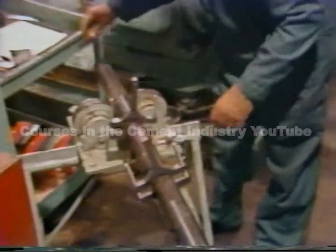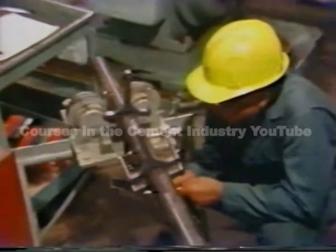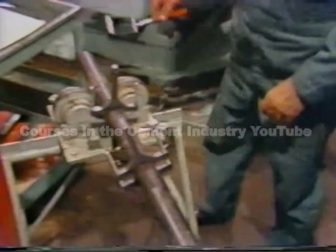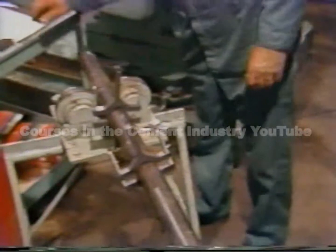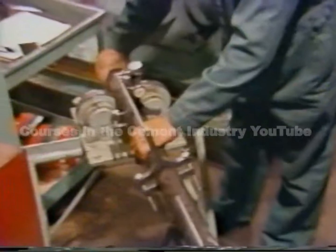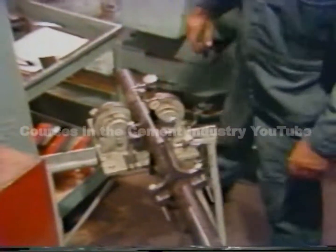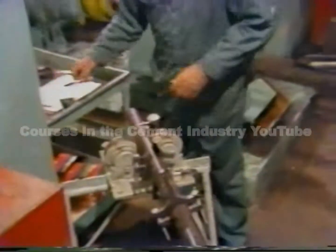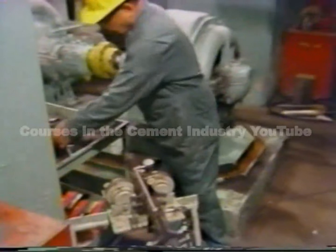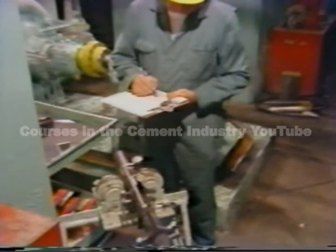After checking the dial re-zeroed at the starting point, he double-checks the reading to make sure that it repeats, and it does. So now he knows that whatever reading he gets in the bottom position for offset alignment must be corrected for sag by 21 thousandths. The sag number is recorded on his data sheet to be used during computations later on.